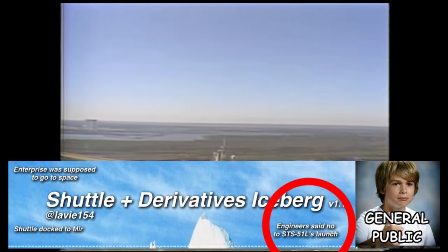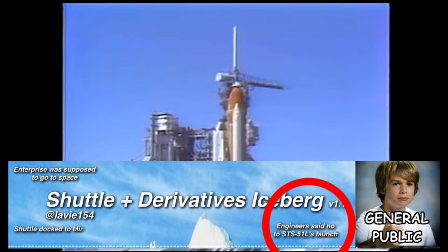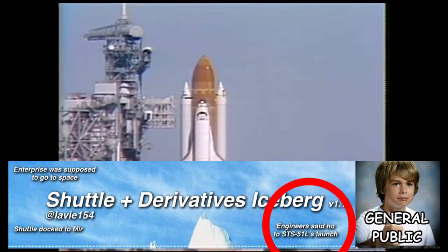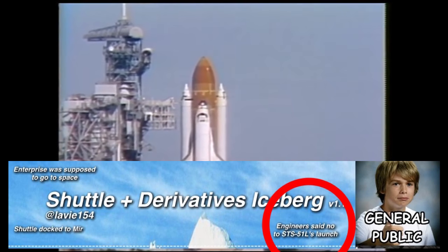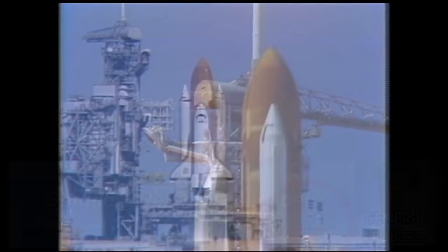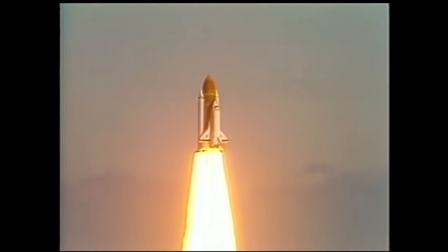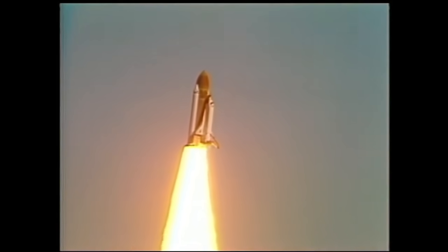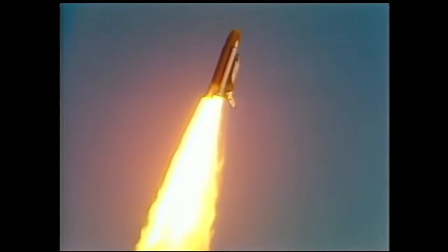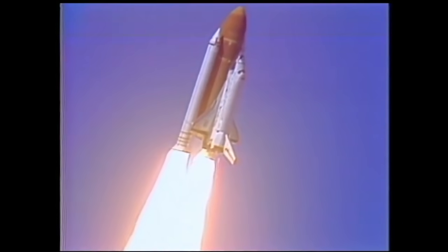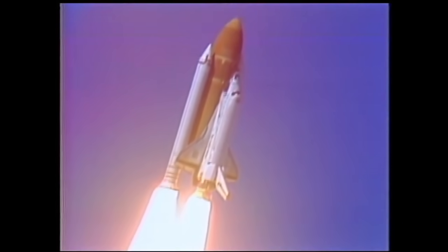Speaking of the Challenger disaster, I don't know how common it is to know that engineers responsible for the shuttle's solid rocket booster explicitly told NASA not to launch on the date of Challenger's final flight. They explained that the extrusion process, in which the rubber O-rings would become heated and shift in their groove to form a seal in the booster's casing, was not guaranteed to work in the projected extra low temperatures of the launch date. However, NASA was being pressured to keep a high launch cadence for the shuttle program, and they caved to political pressure, launching Challenger to its doom in January of 1986.